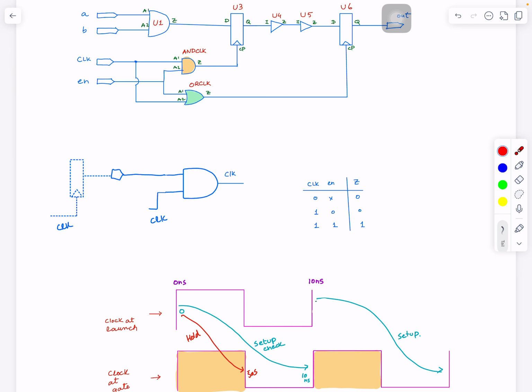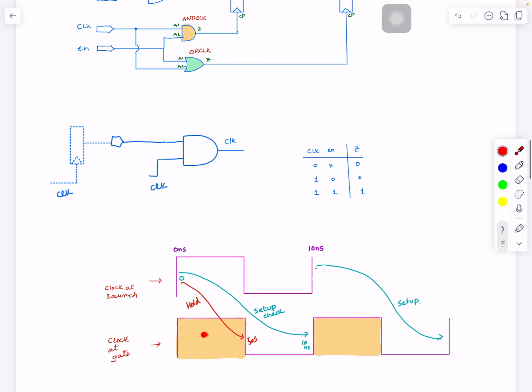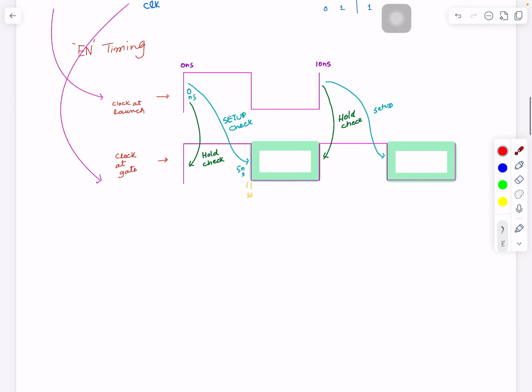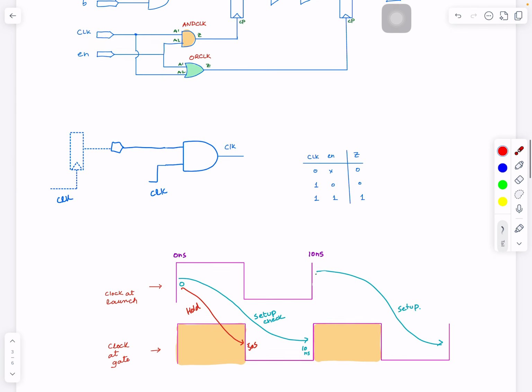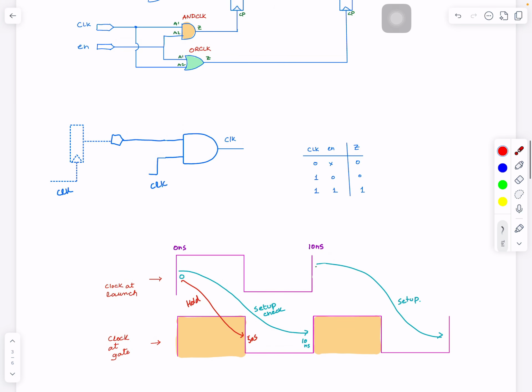So in other words, enable is controlling the output only during the high phase of the clock, which is this one that I highlighted. By the way, the previous one highlighted was the active phase. In the AND case, this is active. So when clock is 1, if enable comes 0, the output clock shape will be different. You understand that?